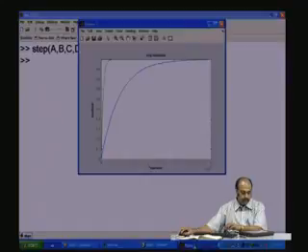So, if we go back and look at the figure, you see that this was the earlier waveform in blue, and in this green color you see the waveform that we now got with these changed parameters. Now, we have reduced the capacitance C, and therefore, the RC time constant is reduced, and therefore, this will be faster.